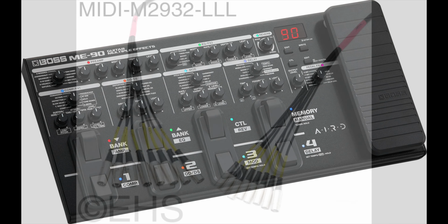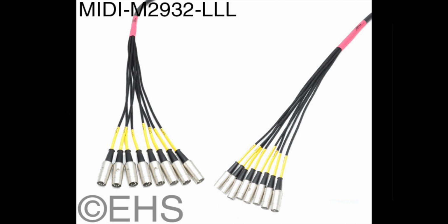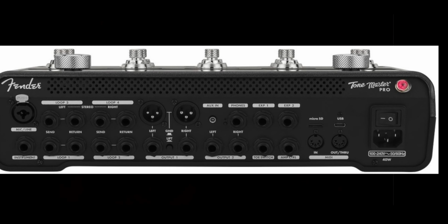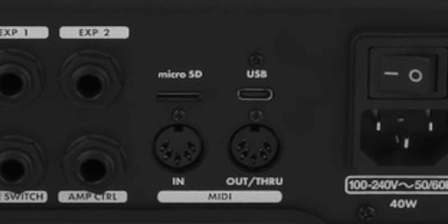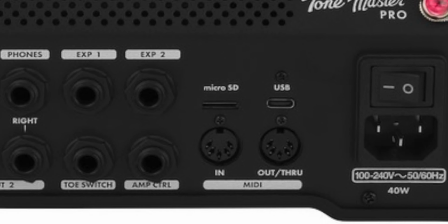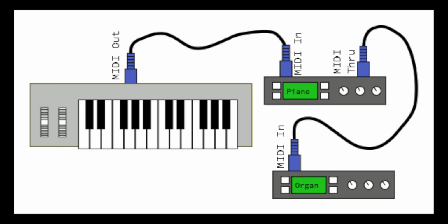ME90 isn't powered. Now a question you might have, if you can control up to 16 devices, how come the Tone Master Pro only has 1 MIDI in port and 1 MIDI out port? How do you connect to all of those external devices? Well, the MIDI out port on most gear also functions as a MIDI through port, so you can daisy chain